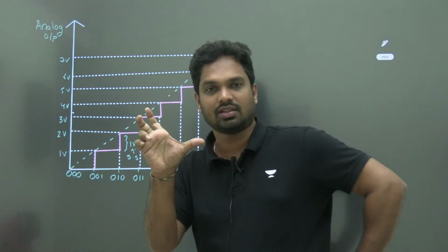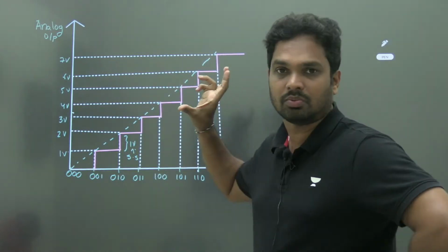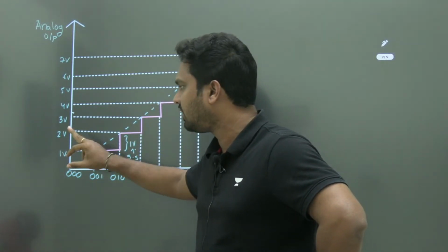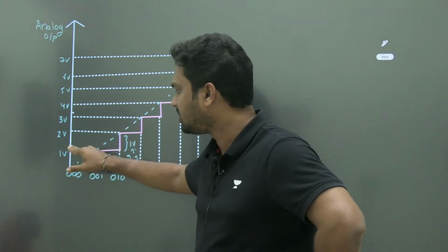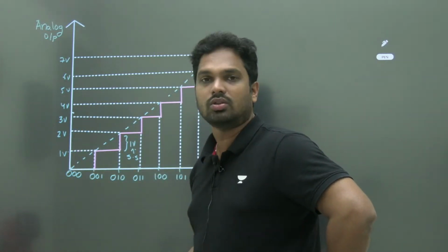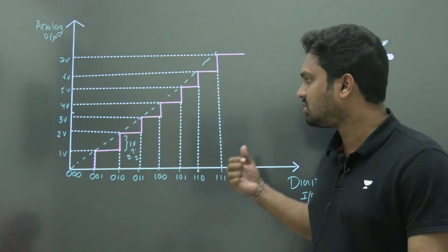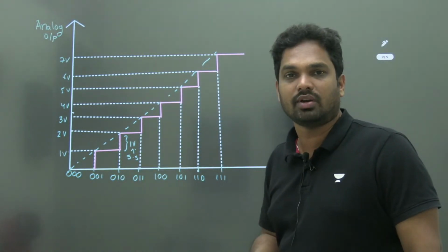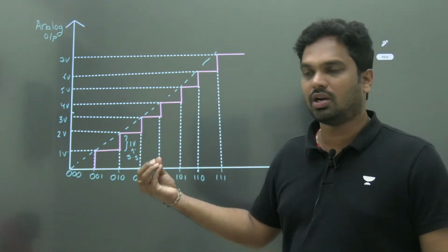Yes or no? Like that, the maximum error will come when the gap is maximum. I cannot represent 1.2, 1.3, 1.5 here; I can represent 1 and 2 only. Signals in between are always represented either as 1 or 2. So there is a possibility of losing accuracy. Similarly, if the step size is 0.2 and you get 1.7, maybe I represent it as 1.8, its digital equivalent.